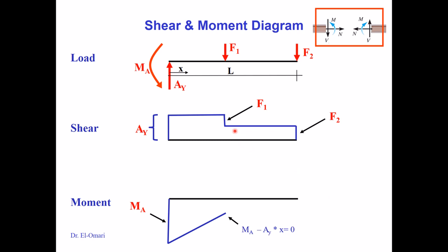And then I know that if this is only the force, and it's supported with this force F2, then there should be no moment, so M is 0. So I know that at this point M should be 0, and there are no major changes. If this is constant, integrating a constant, you get a linear, then you just connect it with this line and you're done. Notice that this is the positive side, that's the negative side.